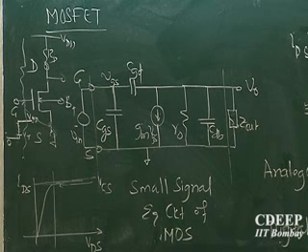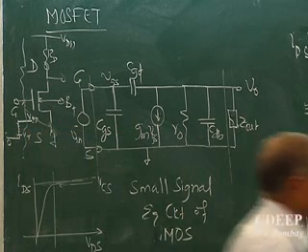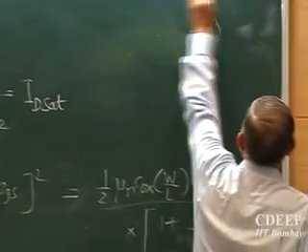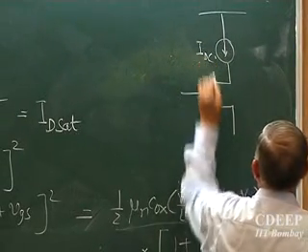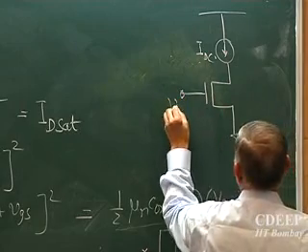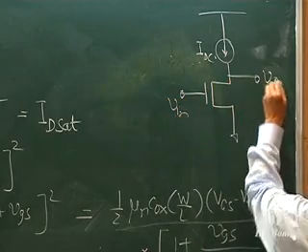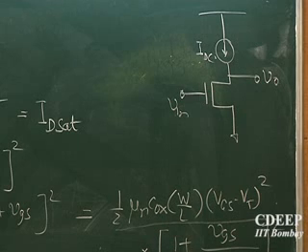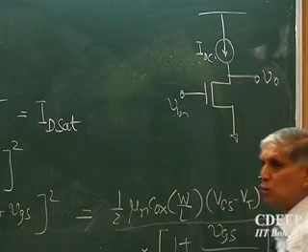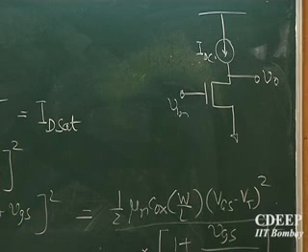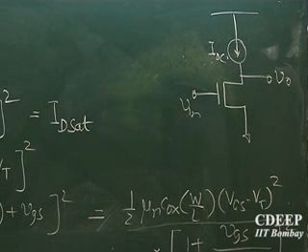The alternate method which all integrated circuit people will use is to bias through currents. This word you should now remember. This is IDC. So it is bias DC, and therefore this current value is so chosen that the device, for a given W, remains in saturation for all input signals. Is that correct? So this is how all integrated circuits will be biased.